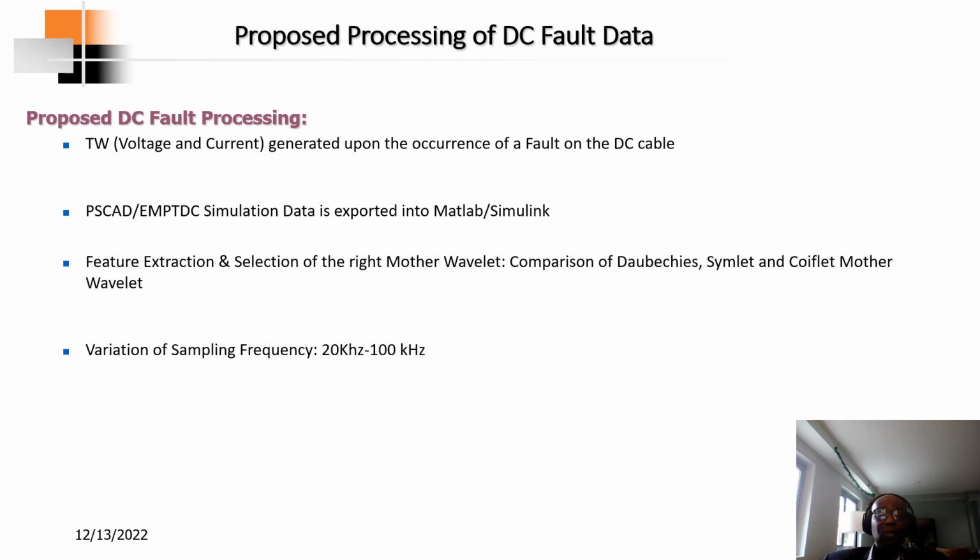Then I will utilize feature extraction. I need to utilize different mother wavelets, simulate and correlate the mother wavelet to perform the feature extraction. And based on that, I'll select the right mother wavelet based on the best similarity with the fault current, and also the optimum decomposition level.